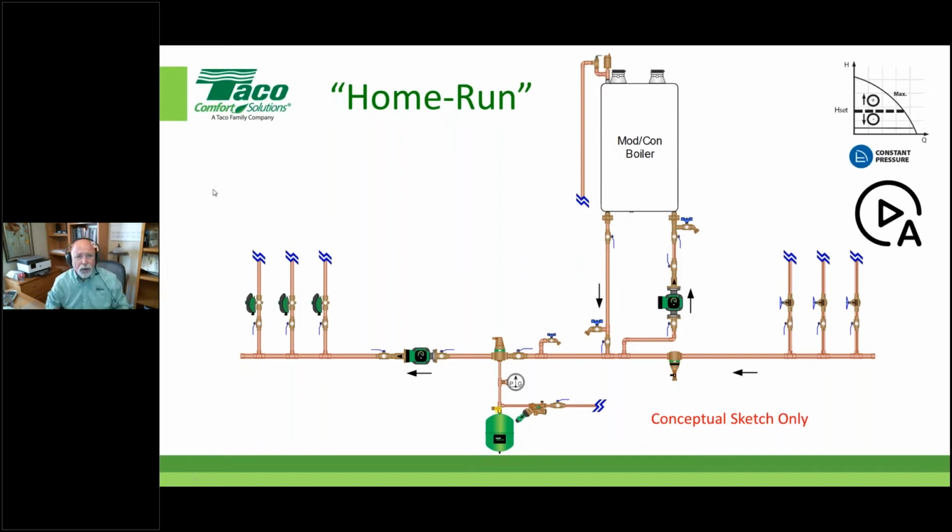We're not going to take the time today to go through the calculation that tells us the following, but if you ever have, you'll understand that one of these zones will set the precedent for the amount of head or resistance this system circulator has to overcome at any time, right? So if one zone happens to be the one that has the greatest amount of pressure drop through it under a design load condition, then by all means, this circulator should be set up to overcome that resistance if that zone calls all by itself. Hopefully everybody's following me there.